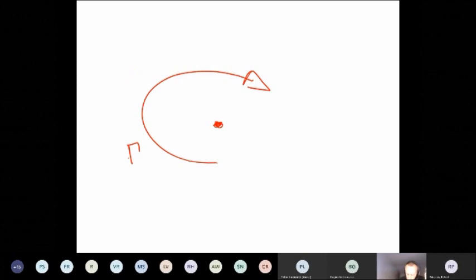My screen's a bit broken on that corner there. What this defines is velocities which go tangent to this rotational flow, with a velocity equal to gamma divided by 2 pi r. And what we do is superimpose multiple of those on the boundaries. This is a basic vortex which defines a circulatory or rotational flow around a point.